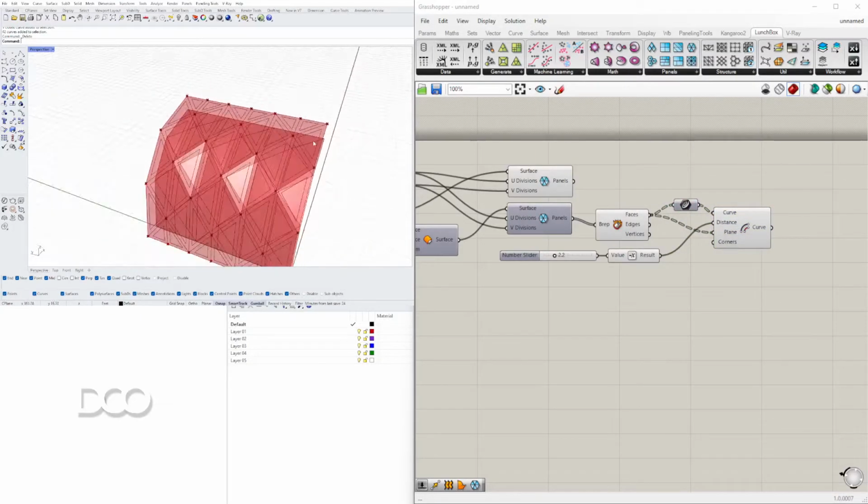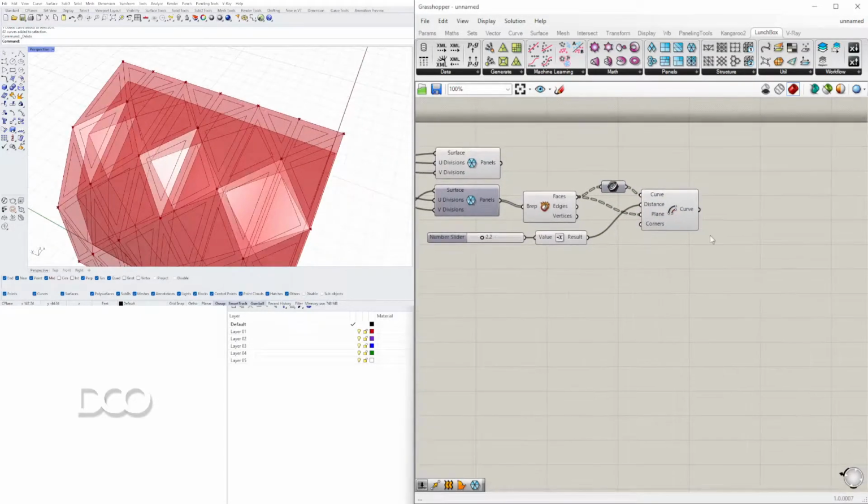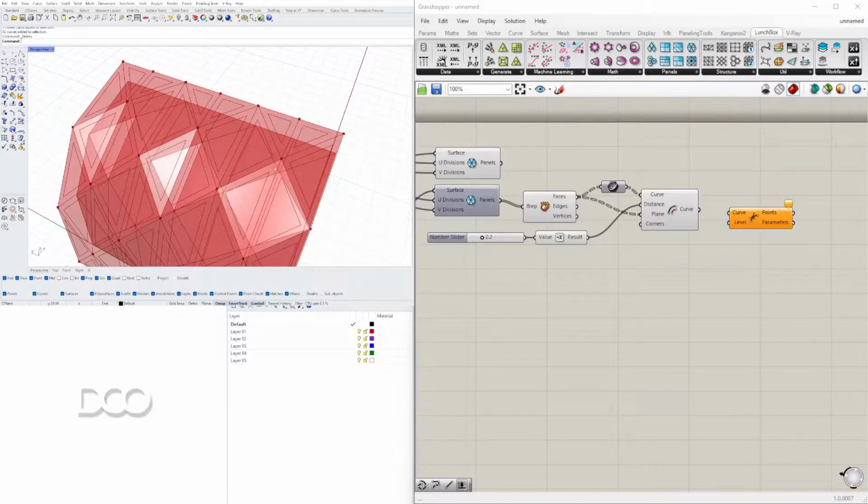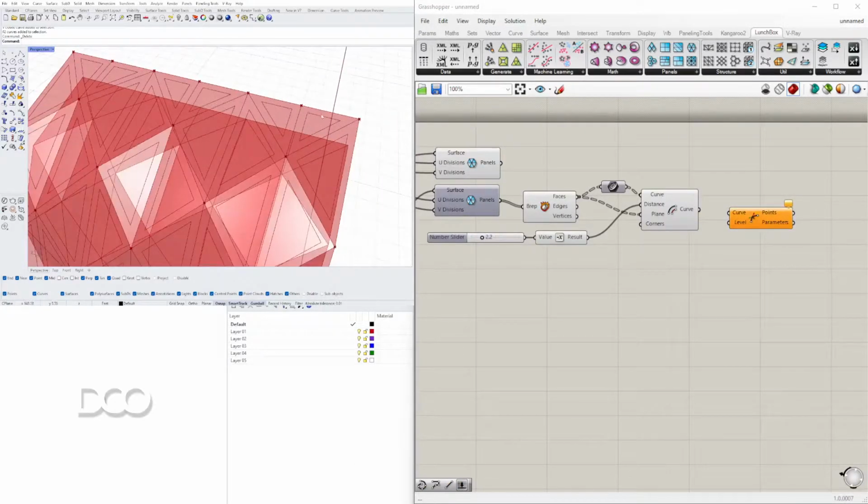And next, we'll bring in the component called Discontinuity. So I'll go here. Discontinuity, what it'll do is it'll take a line, and wherever it's discontinued, which means that if this is a polyline, it'll give you a point, one here, one here, and one here. Basically, wherever the line turns, you get a point.